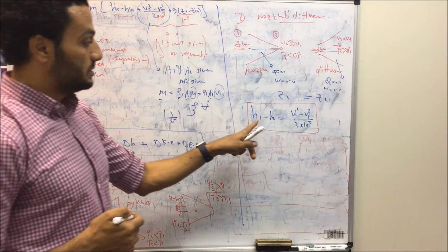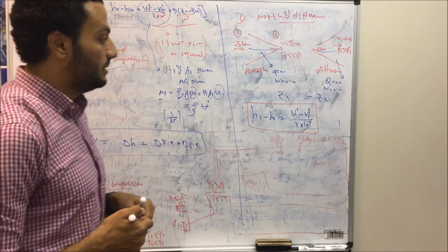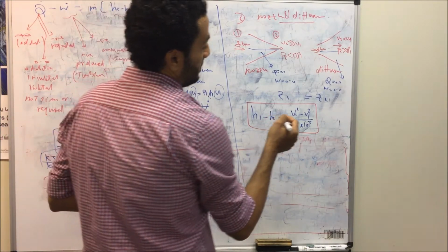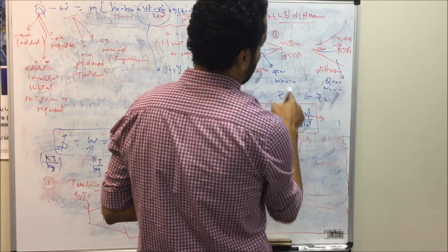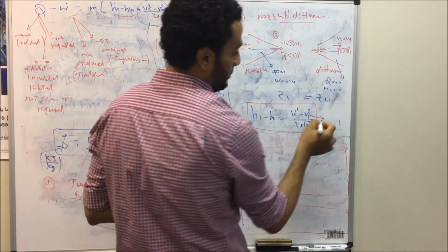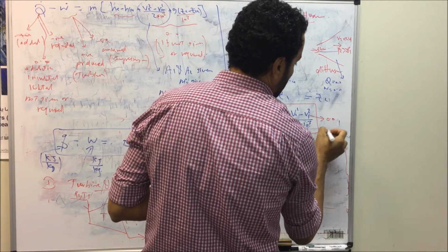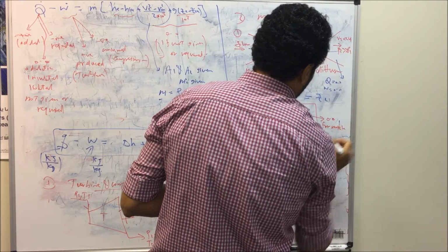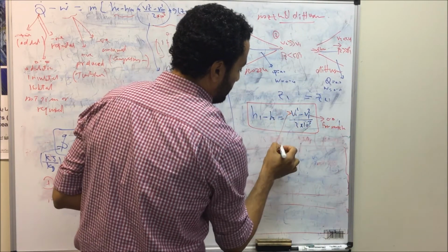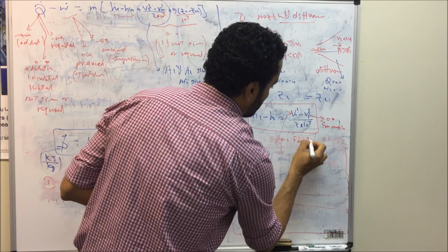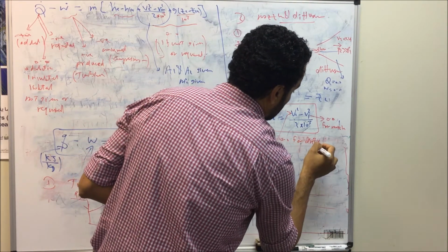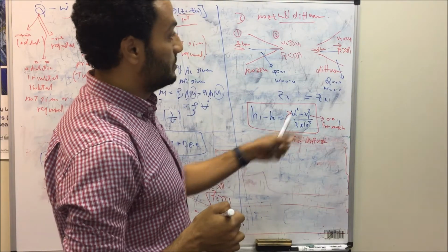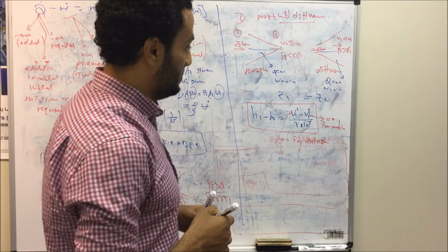The equation will be reduced to enthalpy at inlet minus enthalpy at outlet equal to V2 squared minus V1 squared divided by 2. And in the case of a nozzle, the velocity V2 is much greater than V1, so we can neglect V1 for the nozzle. And for the diffuser, V2 can be neglected, as the velocity V2 is much less than V1.